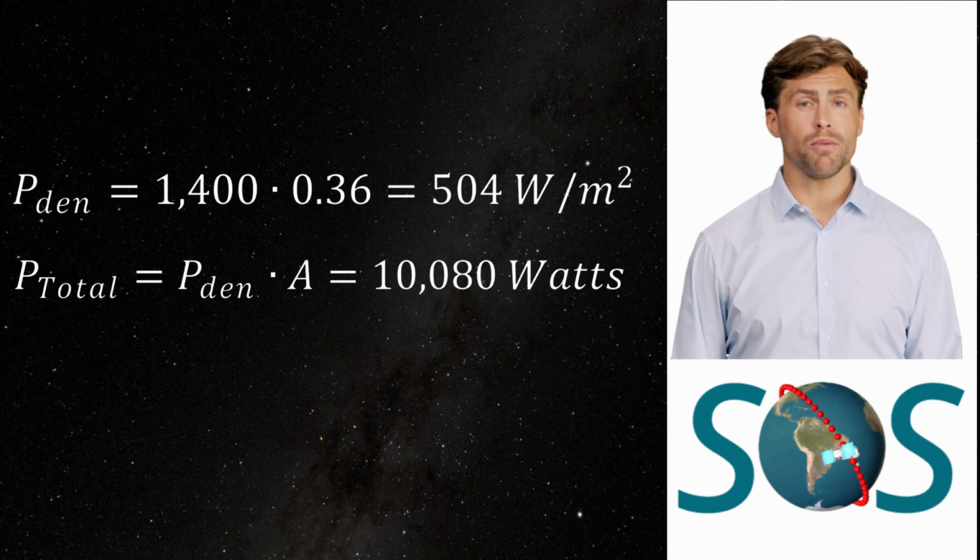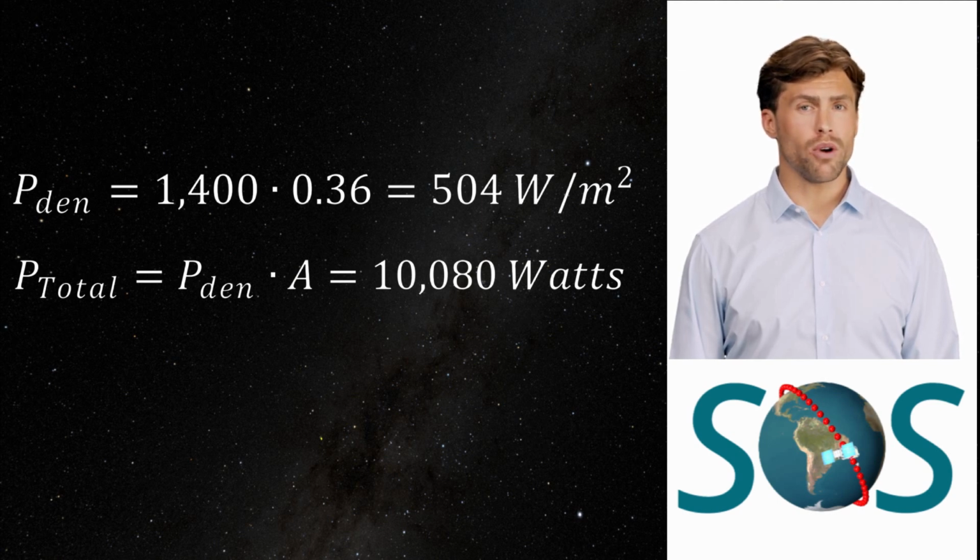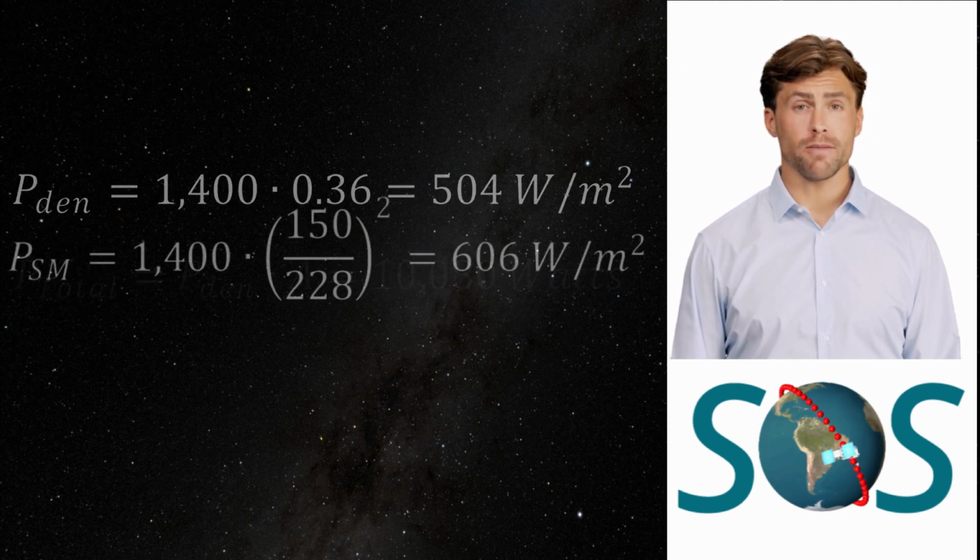Here's another example. Assume that you're designing a satellite to orbit Mars and provide continuous communication between Mars and Earth. The satellite will consume an average of 8 kilowatts of power. Batteries will be used to provide power spikes and will charge during periods of low energy usage. The solar array will have 36% efficiency in converting solar energy to electrical energy. How many square meters of solar panels will you need?